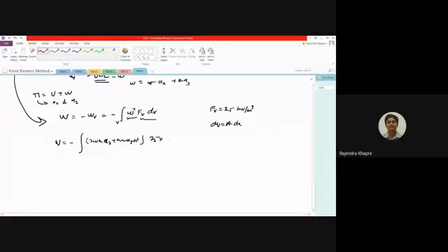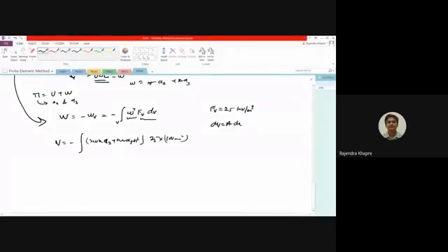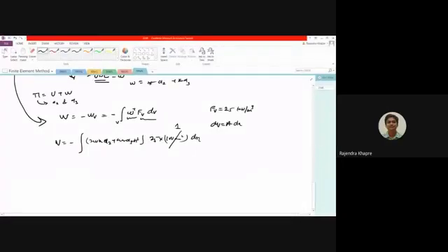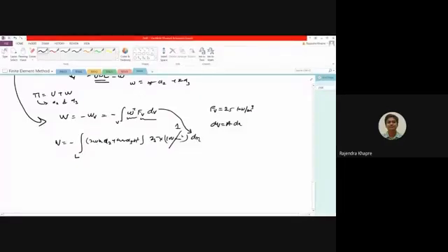Okay, and if the cross section area of the beam is given to you, so let us say area of the beam is given as 100 millimeter square, for example, you can write this value over here into dx, and if this is not given, in that case you can always assume this value as unity. Okay, and since in place of dV we are writing dx, this will be integrated over the length now. Okay, so in this way you have to convert the volume load into the form of a UDL, you can say, and then you can continue ahead.